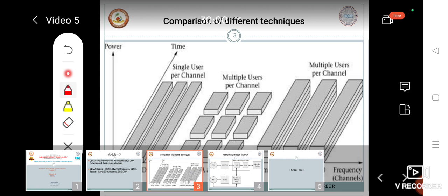The TDMA scheme goes one step further by dividing up the spectral allocation in time slots. Now, each user must confine its transmitted spectral energy within the particular time slot assigned to it. For this case, the mobile and the base station must employ some type of time synchronization. This technique increases the spectral efficiency and spreads its transmitted energy, at the expense of each user's total data rate.